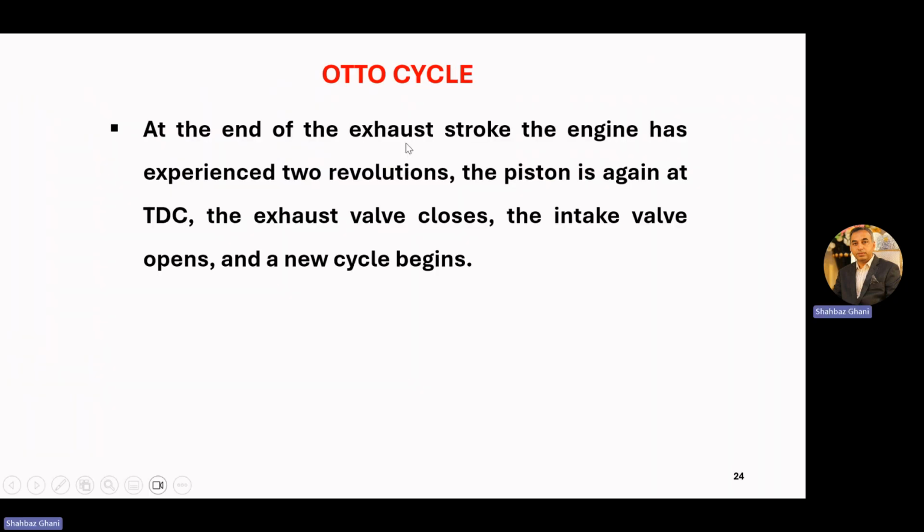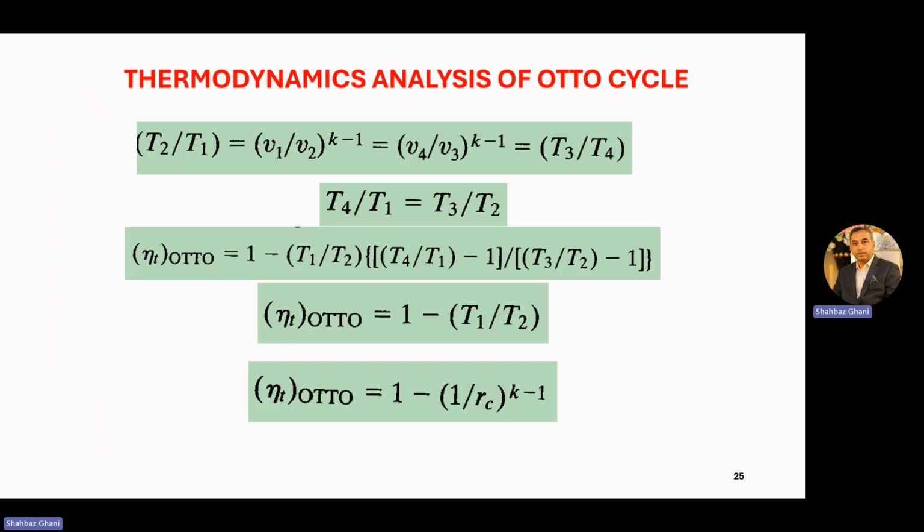At the end of the exhaust stroke, the engine has experienced 2 revolutions. The piston is again at TDC, the exhaust valve closes, the intake valves open, and the new cycle begins. So again, the same repetition and same processes.